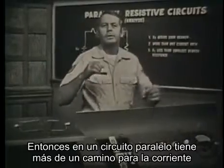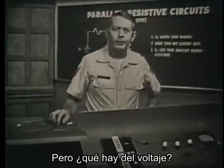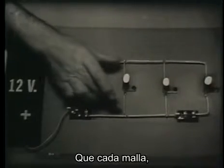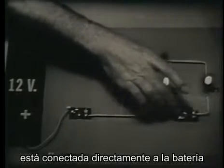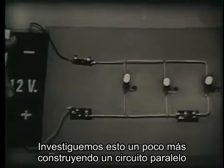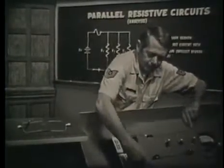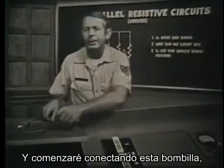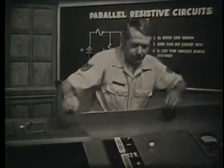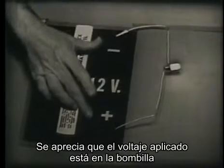Okay, so the parallel circuit has more than one path for current. But what about the voltage? Well, notice on this trainer that each branch is connected directly across the battery. Let's investigate this further by building a parallel circuit. Now, I'll take this one out, and I'll start by connecting one bulb across the battery, like this.